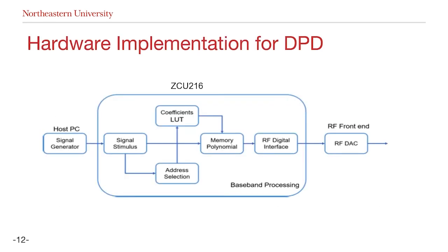And this is the hardware overview of our design. The DPD core is actually running on the FPGA like shown here. Instead of our previous test bench, the FPGA solely served the purpose of a PA. The test signal on the left is generated from a host PC and sent to the board through the Ethernet.